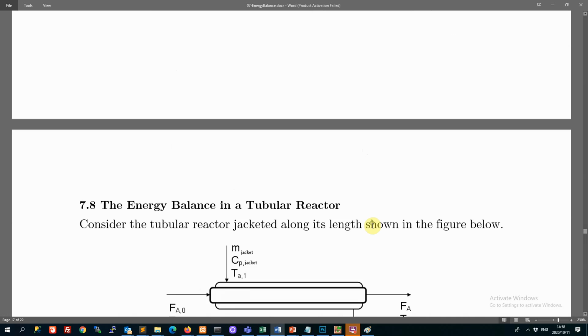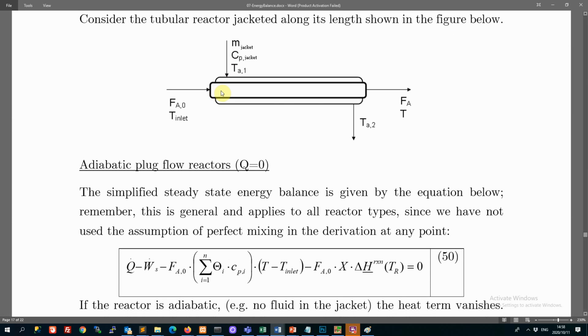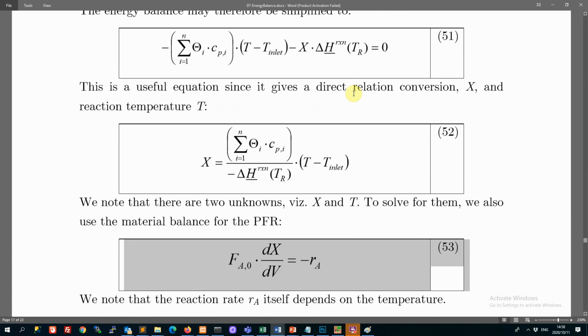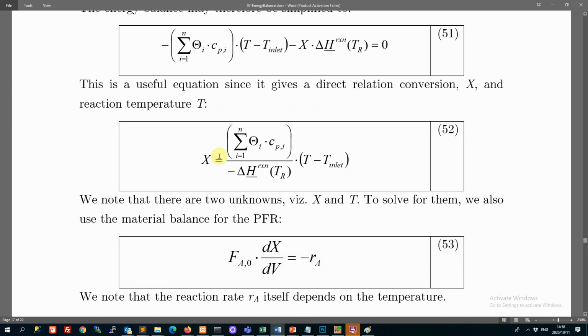And so as we look down this tube, temperature is changing down this tube. And now if it's an adiabatic case, we can just go ahead and use this nice equation. So in the adiabatic case, this equation applies, and that means we can change this equation around, bring T across here and move X in there. So for the current value of X, there is a current temperature.